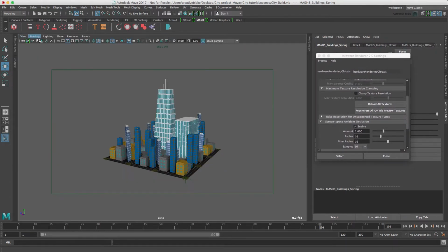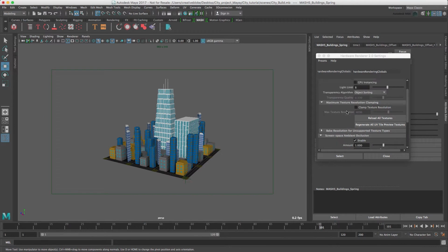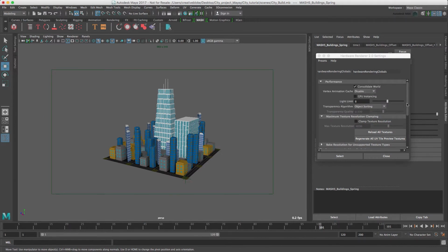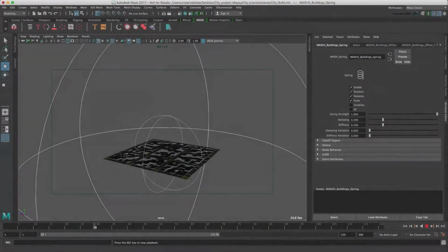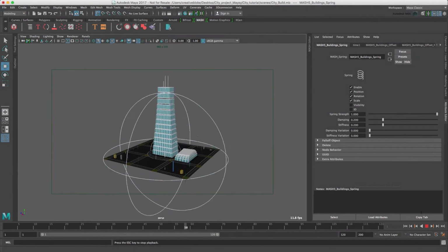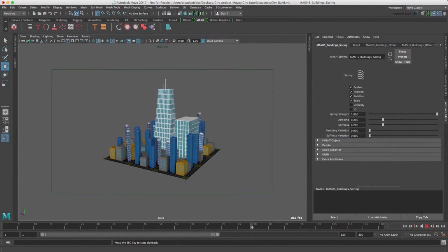Just going to close the outliner so we can see it a bit better. There we go. Then scroll down to our anti-aliasing and switch on multi-sampling anti-aliasing, and our sample count is set to 8. On some hardware it may be higher, but for this machine that's absolutely fine. When we press play, dependent on your hardware, the animation should still play at a brisk pace, even with these viewport settings, especially when compared to an equivalent scene in Cinema 4D.